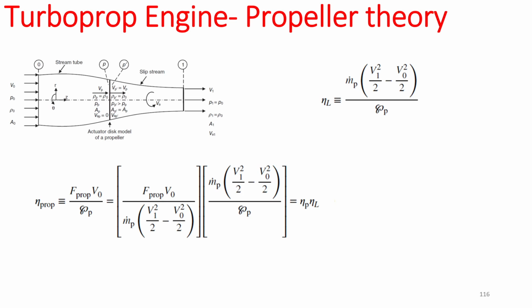Okay. What does the denominator represent? Shaft power that is provided to the propeller, right? So we are comparing the efficiency of the propeller, or we are actually comparing how effectively the propeller can change the kinetic energy, right? Can change the energy of the fluid compared to the energy that is provided to it. Does it make sense?